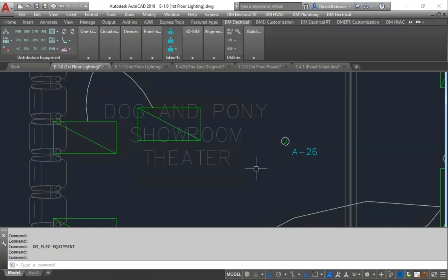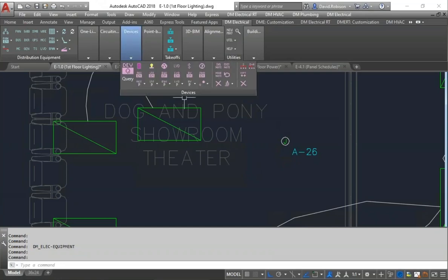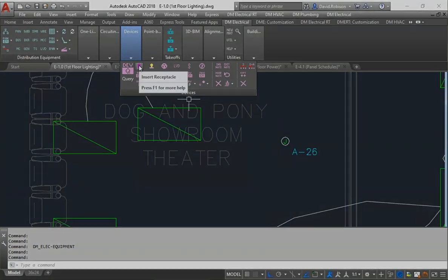So those are the 3 ways you can do junction boxes, depending on what you want to do. Typically, what happens is people try to use this junction box, and it actually can't take a load, but they really wanted to put a load on it, and the correct answer is to use a receptacle or a piece of equipment. It turns out this junction box functionality, while interesting, is not frequently used. Generally, when people do a junction box, they're really looking at equipment connections and receptacles.